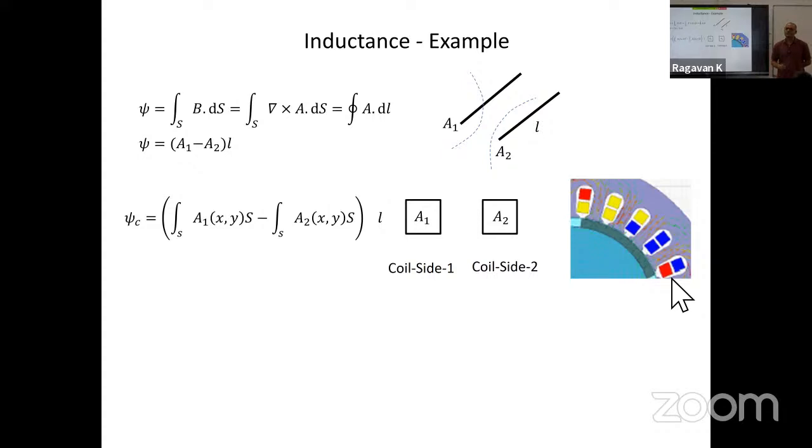By modeling, I'm saying the bars are shorted. Like I said in the earlier slide, we also add the rows corresponding to electrical connections. That means the connections related to the end ring are given to the model. Now on this kind of model, if the default inductance estimation algorithm is run, will it give the actual inductance of the winding? Another question.